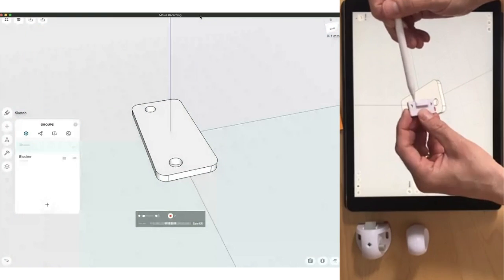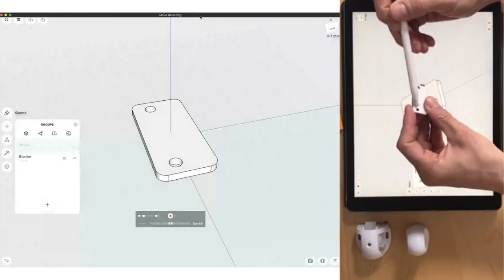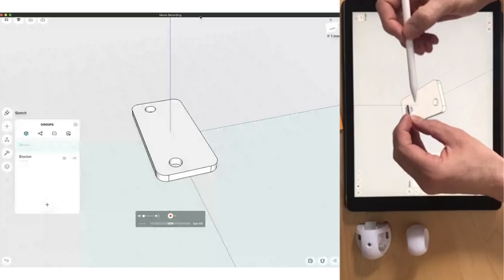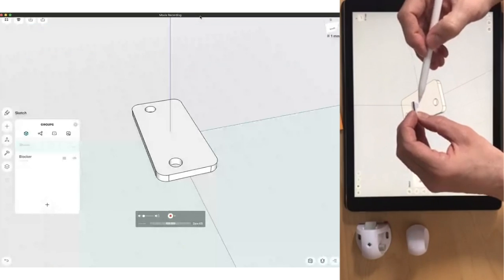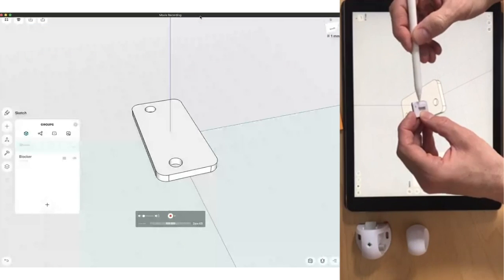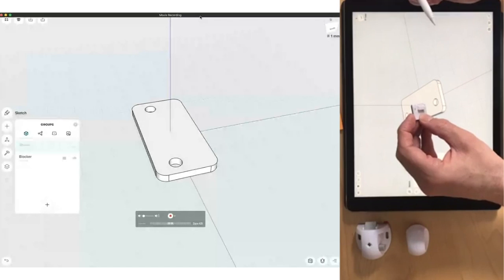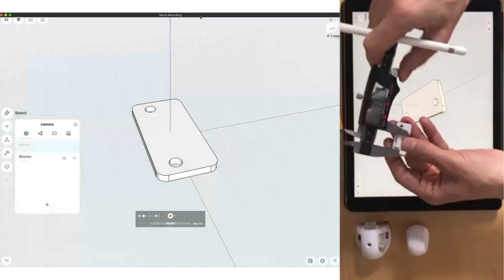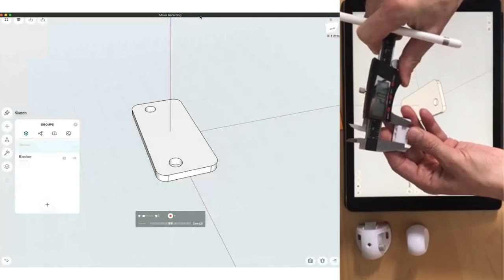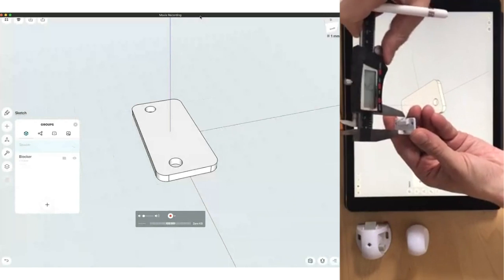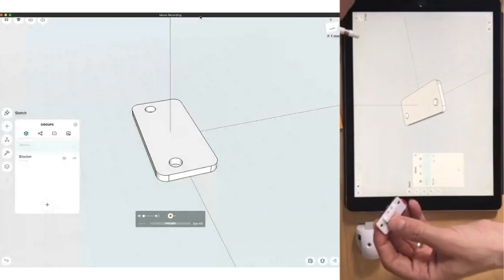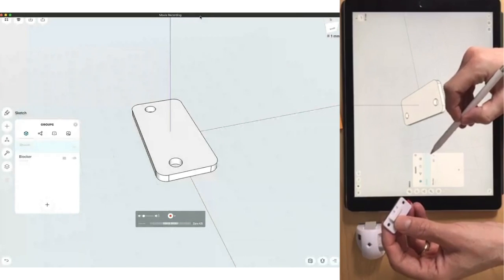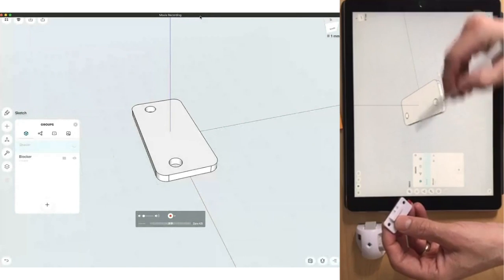Now we have a piece here on top that is not only extruded but slightly shifted. So essentially it's just a rectangle, and then we cut the sides. So what I need to know is how wide is this rectangle? 20. And how deep is this rectangle? Looks like 7.5. So this I can put on